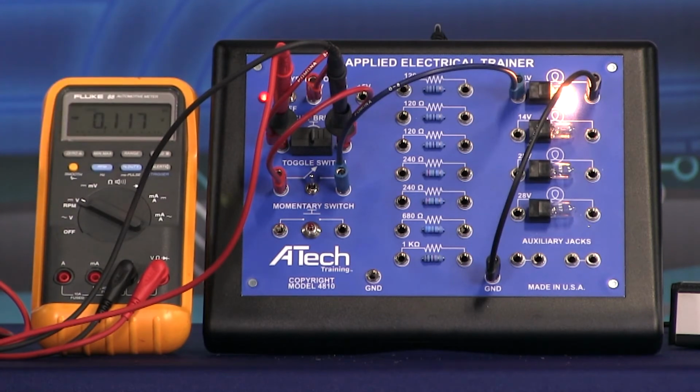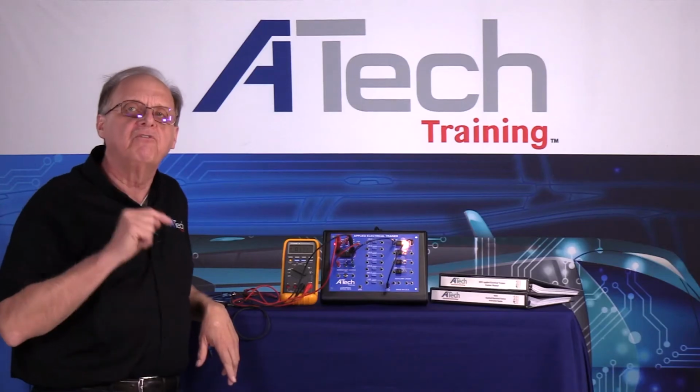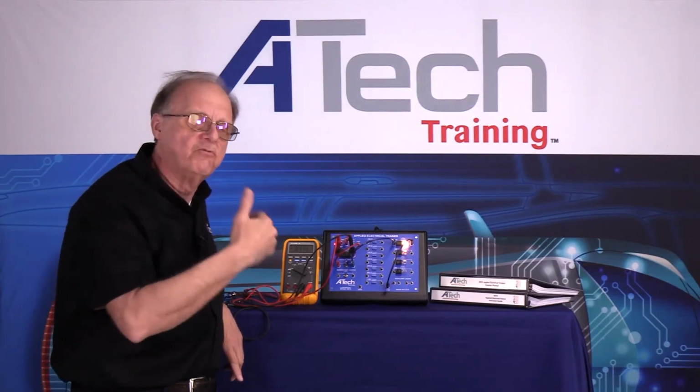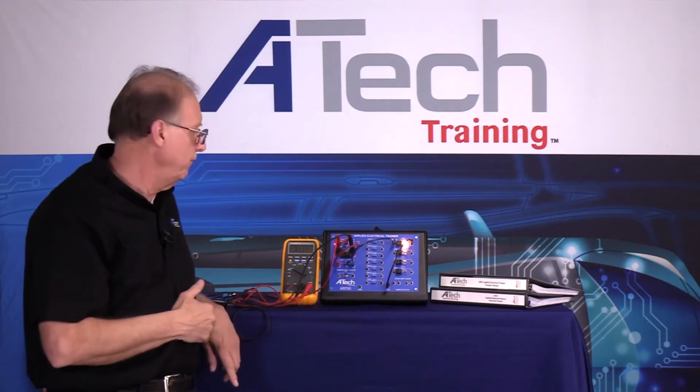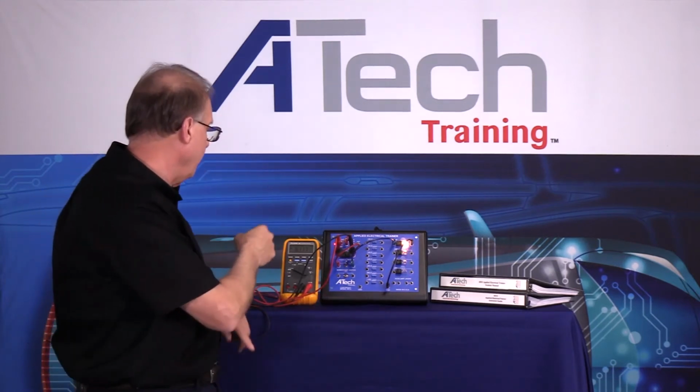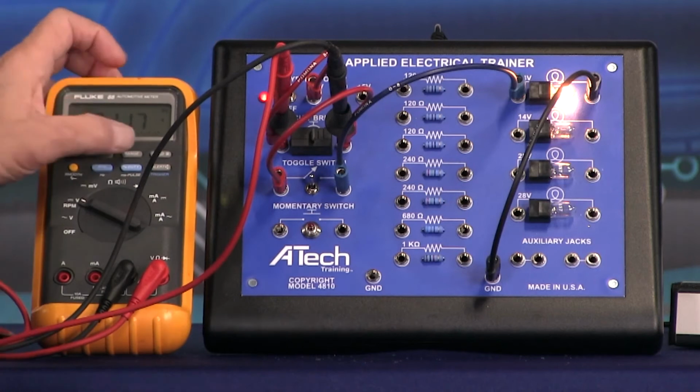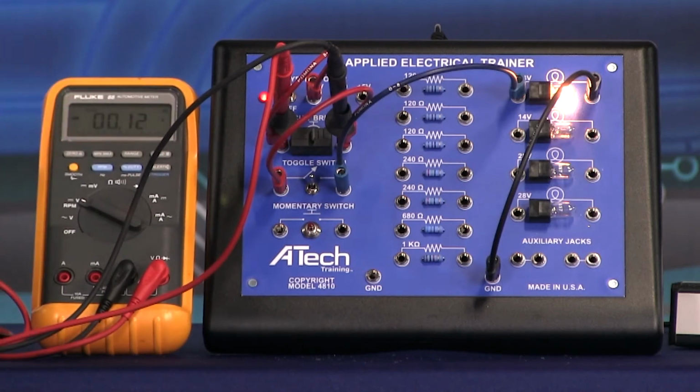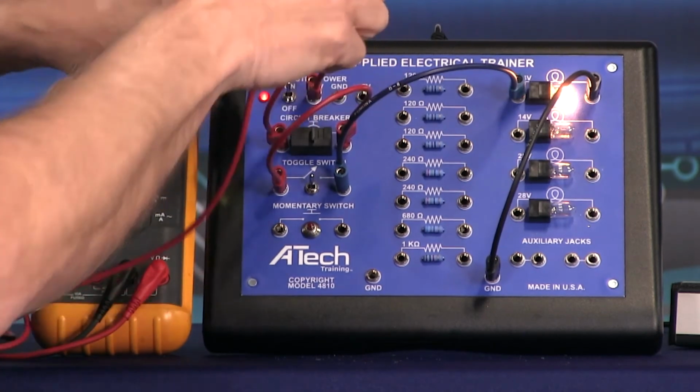And right now it says 0.117 volts. Sometimes when you're using all these auto range tools, you still have to hit the range button. You need to address that with your students to make it a little easier to use. So I have dropped, and we'll go back to the range I was before, I have dropped 0.12. So I know I've dropped a little voltage across that.